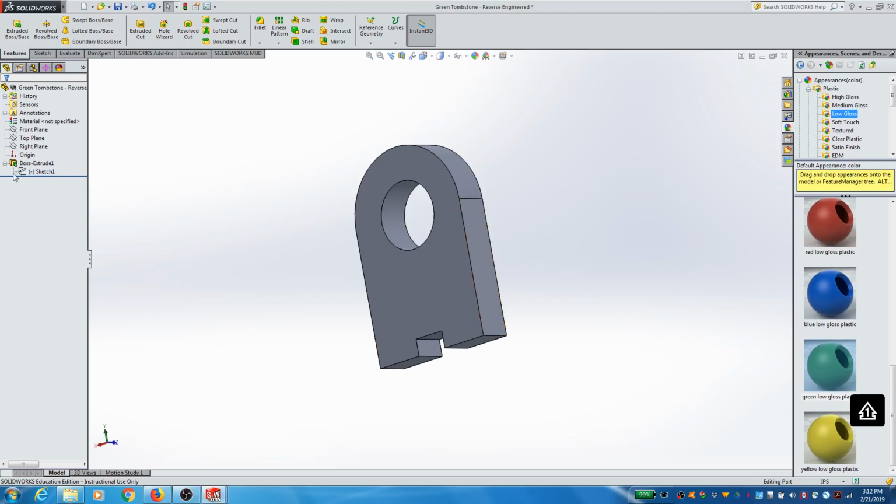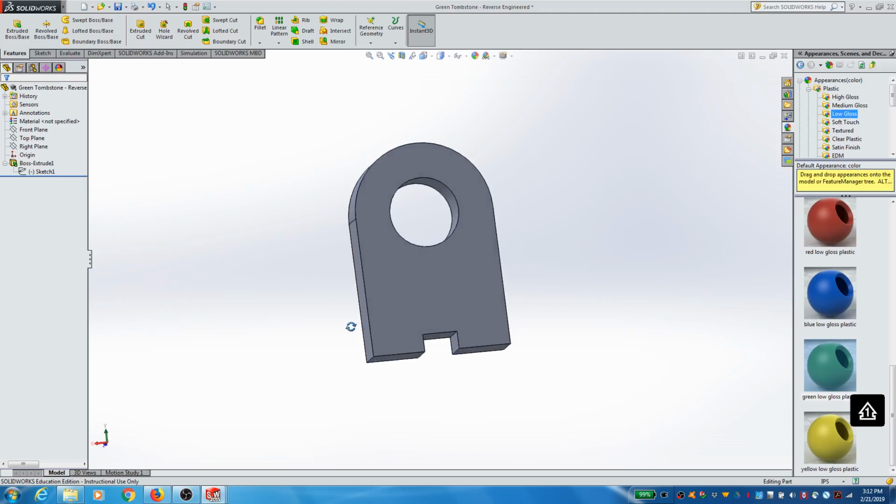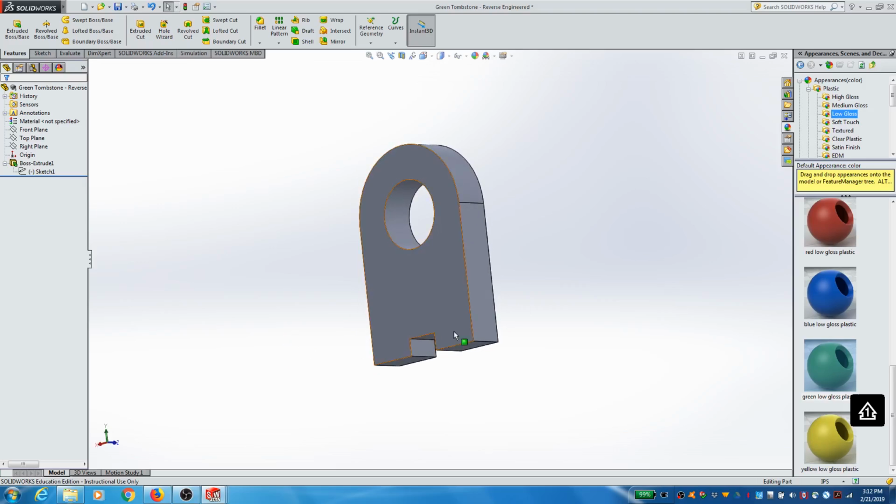Okay, there's 2 ways to add fillets. Let me show you first the way to do it in 3D, and then we'll go back and do it in our 2D sketch. So I'd like to round this edge and this edge, right? And the rounding is actually going to be 0.1 inches, folks. That's kind of like a medium level rounding to just take the sharp edge off.